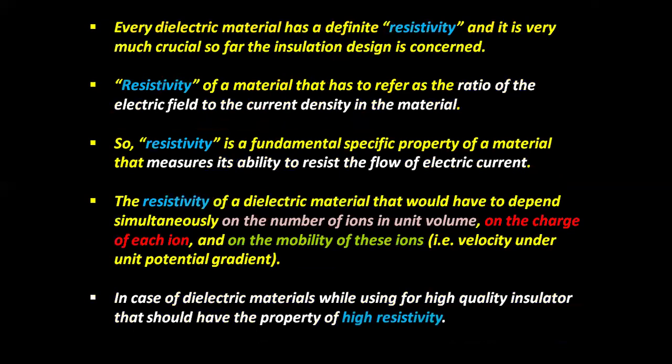Every dielectric material has a definite resistivity, and it is very crucial so far as the insulation design is concerned. Resistivity of a material refers to the ratio of the electric field to the current density in the material. So, resistivity is a fundamental specific property of a material that measures its ability to resist the flow of electric current.